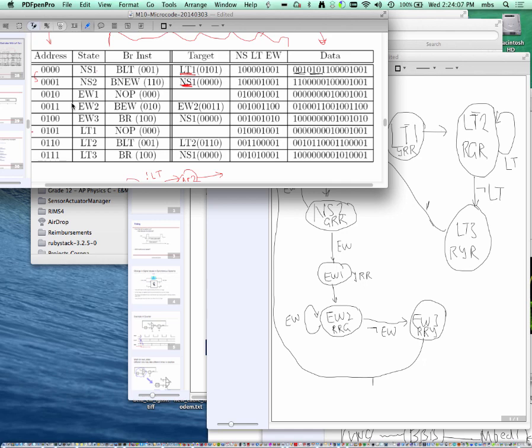The only branch instructions we had here are those which let you either go to an address under some condition or go to the next address. So we can only do two-way branches. Last time I'd also discussed that with some additional logic we can have, like the example I had, a four-way branch. Those are relatively rare. But the point is that unlike when I'm drawing a state machine arbitrarily, where I can have any number of outgoing edges, here I'm limited by what instructions I have.